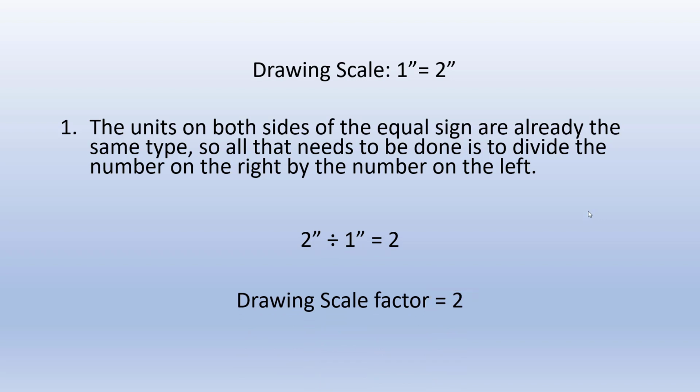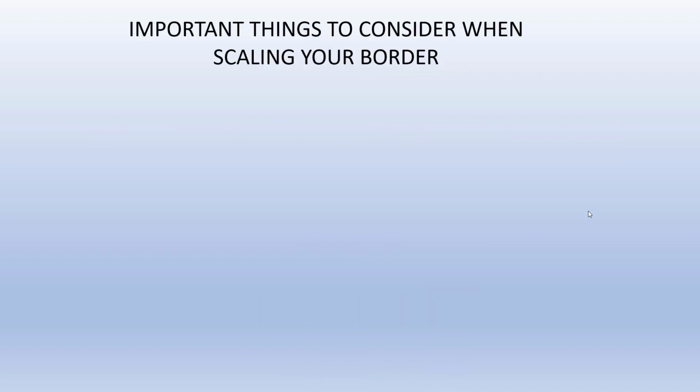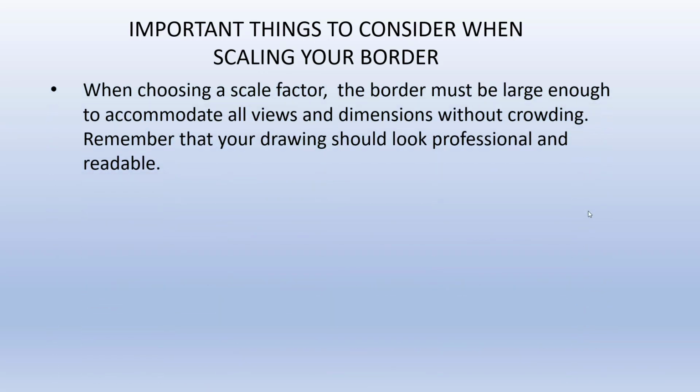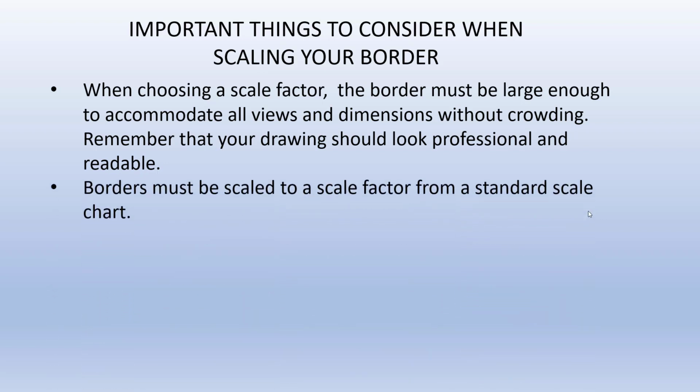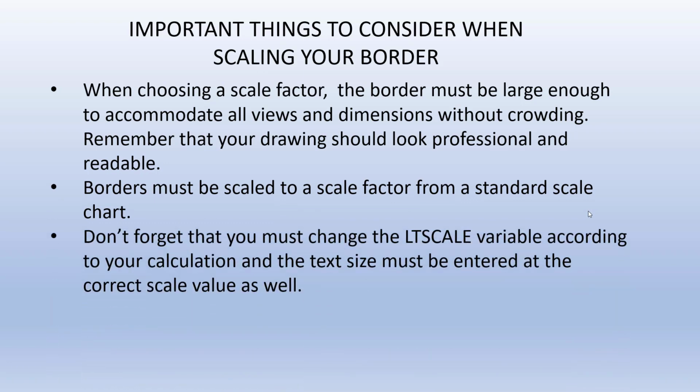In wrapping up this tutorial, there are some important things to consider as shown in the bulleted list here. They are: when choosing a scale factor, the border must be large enough to accommodate all views and dimensions without crowding. Remember that your drawing should look professional and readable. Borders must be scaled to a scale factor from a standard scale chart. Don't forget that you must change the LT scale variable according to your calculation, and the text size must be entered at the correct scale value as well.